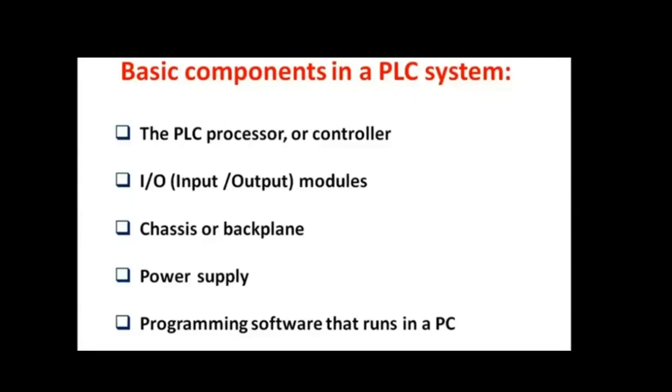IO module, next one is chassis or backplane, next one is power supply, and then programming software that runs on PLC. So the basic components, the first one is the PLC processor or controller. Processor is the most important part, which will process the input signals and whatever program is written inside the memory of the PLC, and it will also send signals to the output to control any process. The processor performs whatever computation and arithmetic operations have to be performed. All these things depend upon the speed of the processor.